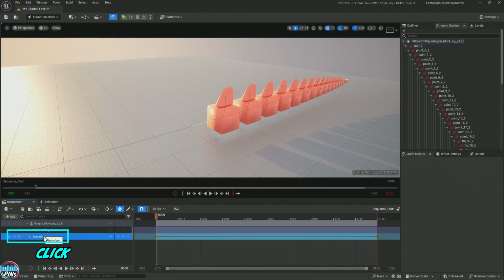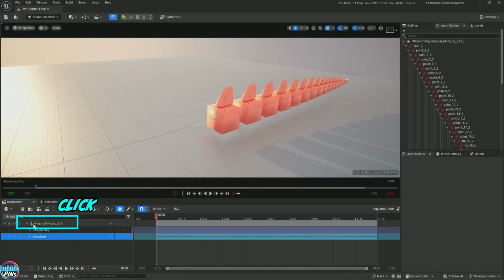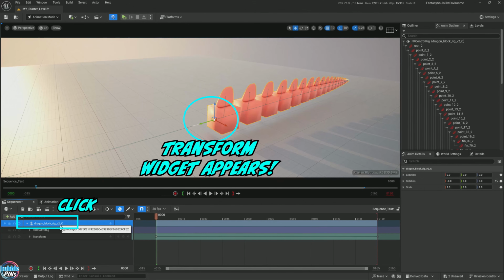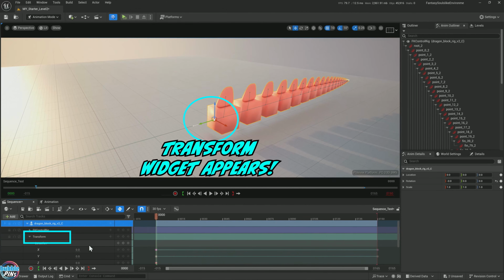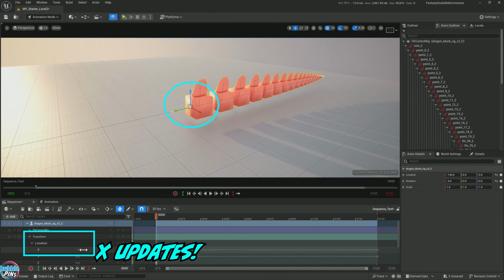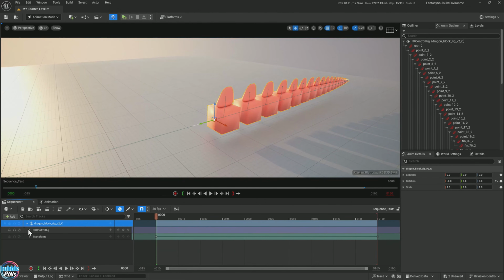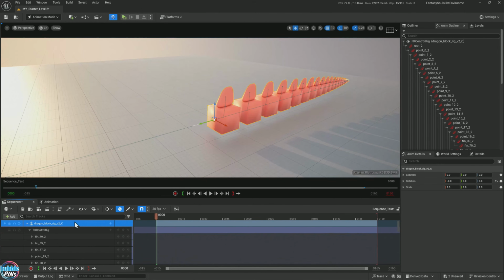You can just click this layer. It's not coming up. Click the top control character layer and then it'll come up. And then you can modify this transform layer. Now I can show you. Now you can see this got updated. Now we don't want that, so let's undo that. I just wanted to show you how you can still click on it if you can't get to it in the viewport, just because there's so many bones in the way. You can still get to it. It's just not as easy, so it's good practice to do the transform layer first if you can.